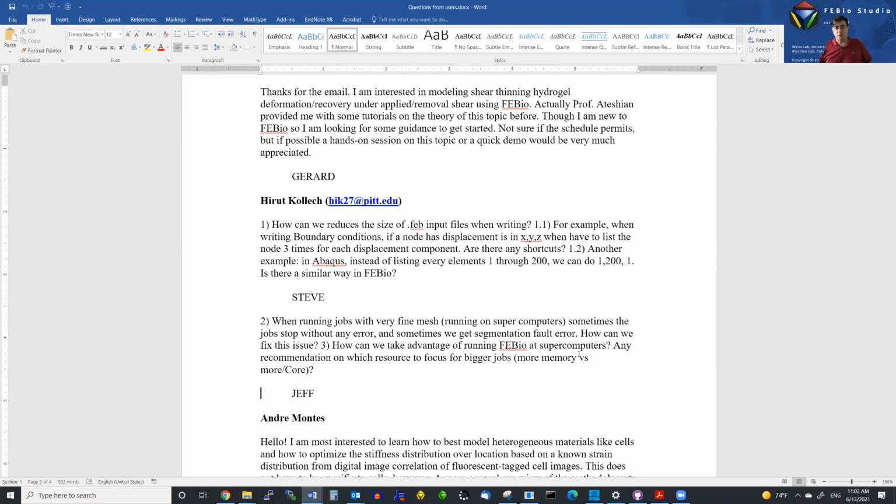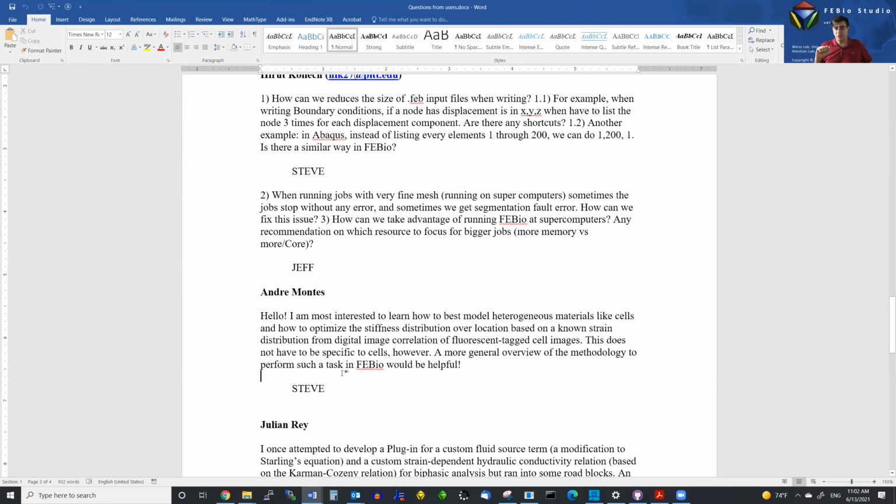Can I comment though? So you're running fluid FSI models, is that correct? No, they're solid. Solid? Yes. Okay, so do they have a large number of elements because the meshing was based on some image-based acquisition, or is this the mesh refinement you actually need? So it comes from multi-photon microscope data, but I was doing the mesh convergence plot. That's why they're larger files. The finer simulations are big. Okay.